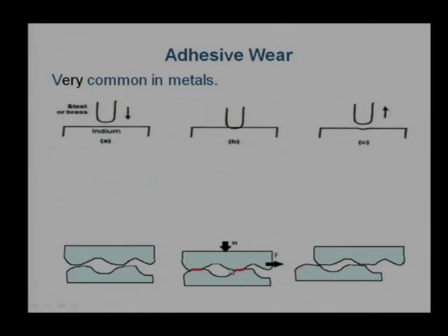Naturally, almost every asperity will be undergoing plastic deformation, and to some extent up to the elastic limit it can easily bend. Now, if we provide some lubricant layer, or there is no chemical affinity between metal 1 and metal 2, then there is a possibility of easy shearing of that surface, and breaking the bonds will be easier. There will not be much wear. Of course, there will be wear, some fragment will still get torn away from the surface. So there will be what we call mild wear, mild adhesive wear.